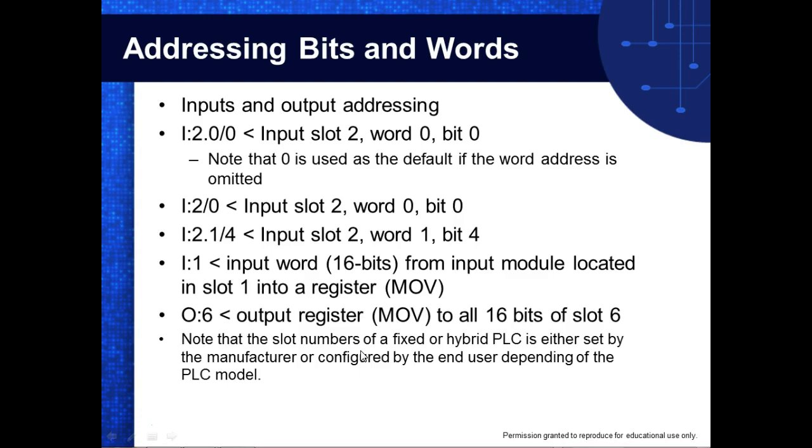And all 16 on the chain. So if we wanted motor number 1 to start, then number 2, and stop number 3, and start number 4, and move this guy, shift that guy, and we had the sequence of events that we wanted our line to go through, you can set it up in a sequence. It's really, really neat. What we can do is we can output a whole bit. Now, it's kind of hard to do this on our PLC because we've only got 8 inputs and 8 outputs, right?